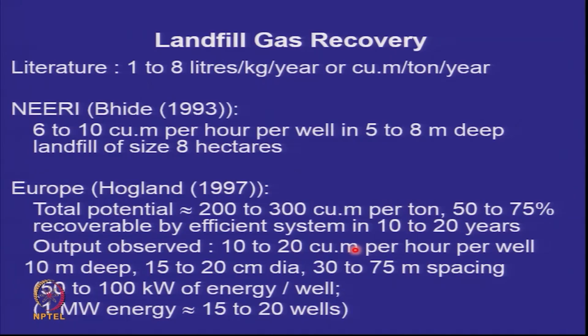So this translates to about 50 to 100 kilowatts of energy per well. Also look at the depth. Here they were talking of a 5 to 8 meter deep landfill, and here they are talking of a 10 meter deep landfill. And they typically have gas wells at a spacing of 30 to 75 meters. So if you have 15 to 20 wells of this kind, you can generate 1 megawatt of energy for 20-25 years. That's the European experience.